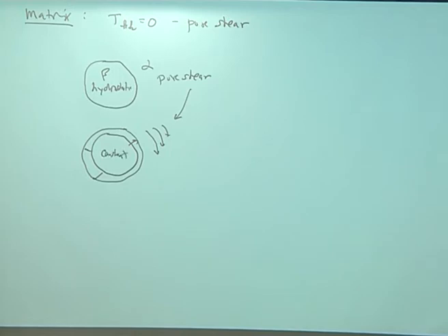It doesn't vary with position, and this is why I think sometimes these elasticity problems, at least to me, are pretty non-intuitive, because you have a hydrostatically stressed body so you just take a particle, you put it in, and it's a hydrostatic stress, a pure dilatational misfit, and you get a hydrostatic stress inside and shear going away.